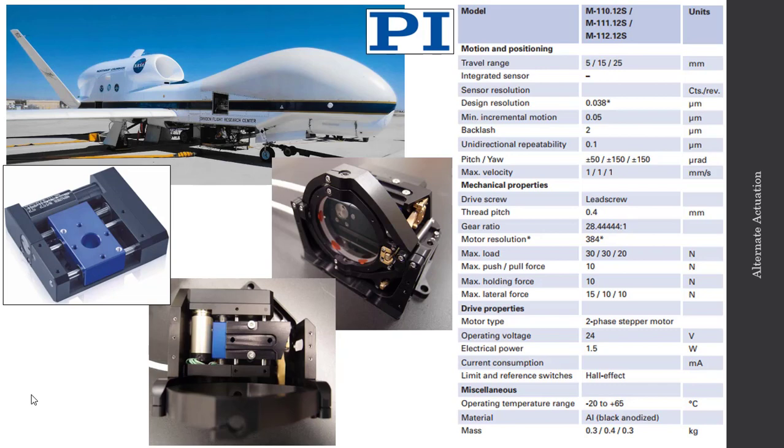This ultimately defines how well we can align the laser beam exiting the instrument with the axis of the telescope in the receiver. Thus, for this particular application, using a stepper motor in a linear translation stage, we were primarily interested in the specifications such as max holding force to be able to hold that position of the mirror throughout flight, as well as the minimum incremental motion.